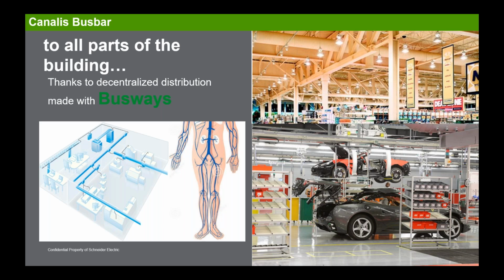You can see here shortly on this image that you can have the bus bar going through, and you don't have several distribution boards or panel boards. You have one length of bus bar, and you can supply the dedicated load from a tap-off or from a small enclosure having the protection. So this is what we call decentralized distribution. As I said, I will have a dedicated slide where hopefully we'll see the main difference between centralized and decentralized distribution.